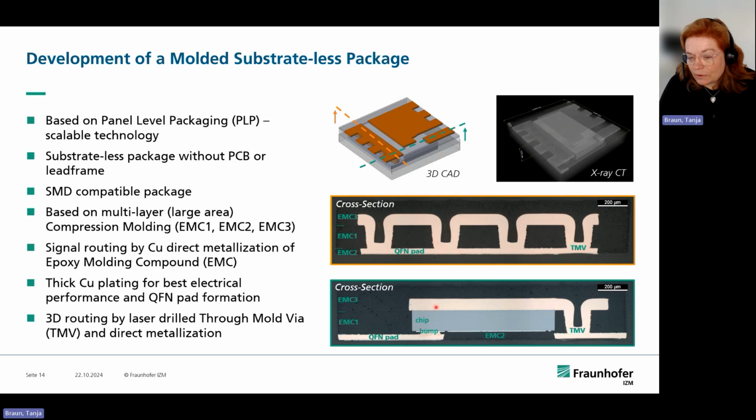And you of course then need to bring the backside contact to the front side. That was also done by direct metallization and a laser drilled blind via to that first metallization layer. And then of course it had to be isolated again, so you do a backside overmolding to have that isolated. Then you also needed the front side metallization step and a back grinding step to access these connecting pads later. So this gives you an idea of what is possible. No substrate included, not even a real RDL, no dielectric material, a whole package only with mold and direct metallized copper. Could be a very cheap solution, especially if you go to a large format.